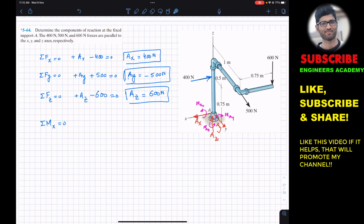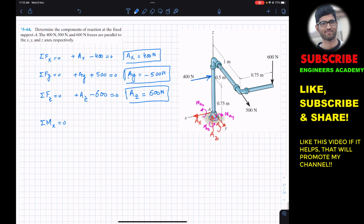So this 500 Newton force can produce a moment about the X-axis in this direction. And this 600 Newton force can also produce a moment about the X-axis in this direction. So we have MAX, which is in the positive X, the counterclockwise moment, so I will write plus MAX.